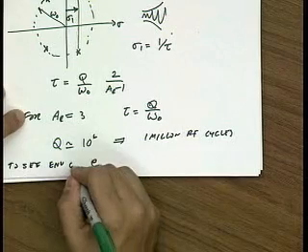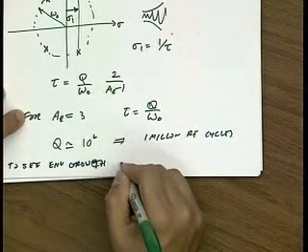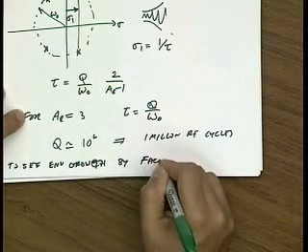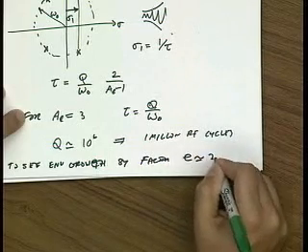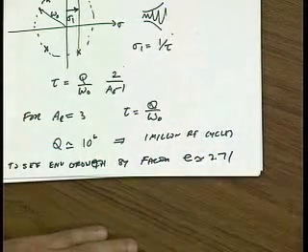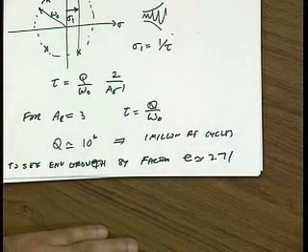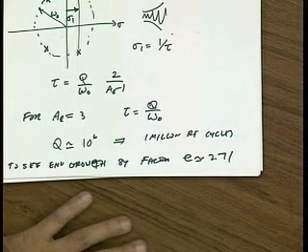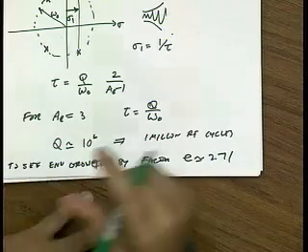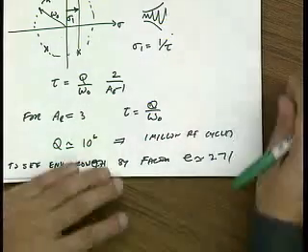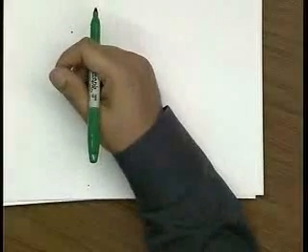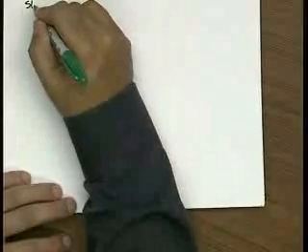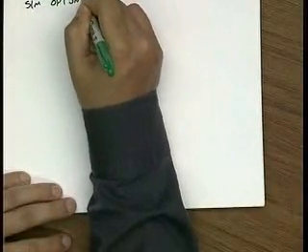Let's say envelope growth by a factor of e, which is about 2.71. So that means that you're going to need several million, tens of millions of oscillations before you actually get to steady state. And so you're going to upset a lot of people using the same computer if you simulate this thing more than once. So there's some options to get around this.